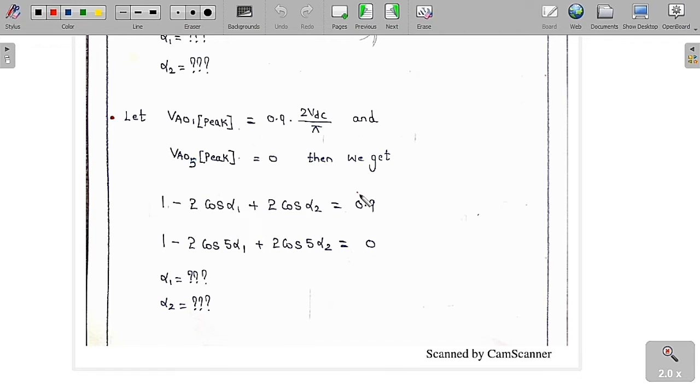Whereas this selective elimination is not at all possible in the one-way switching. So with one switching in quarter cycle, this type of selection is not present, as you can already see. This type of selection is not possible with one switching in quarter cycle, whereas with two switchings in quarter cycle, yes, we can eliminate whatever harmonic we really don't want. So therefore, we can eliminate it by this process.